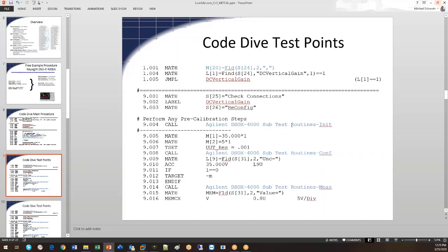And you can see in here where we make out to our routines call, we're going to make out an init call, which is going to run any steps we need to do before we can run that calibration. So if I needed to zero and calibrate a power sensor, I could do it in that init function.